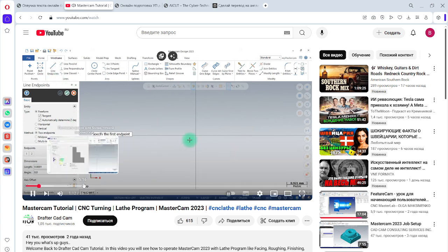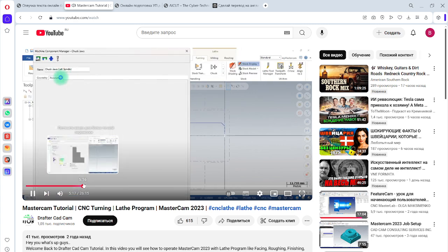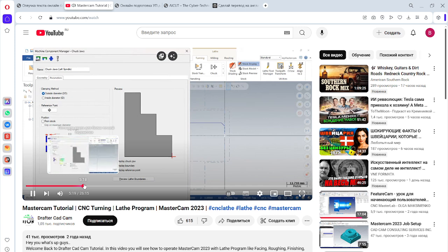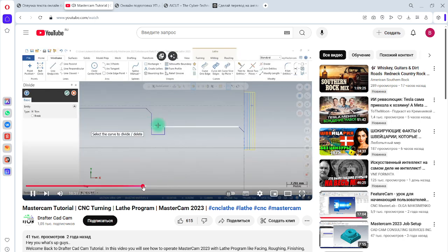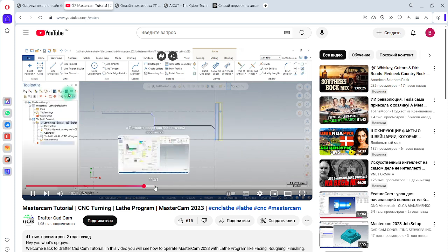Okay, so you can, and on the parameter you can define the diameter is 32 millimeter, like the diameter of this raw material. After that, the position of the chuck jaws is okay. The groovings get already done, so we can start to roughing this sketch.